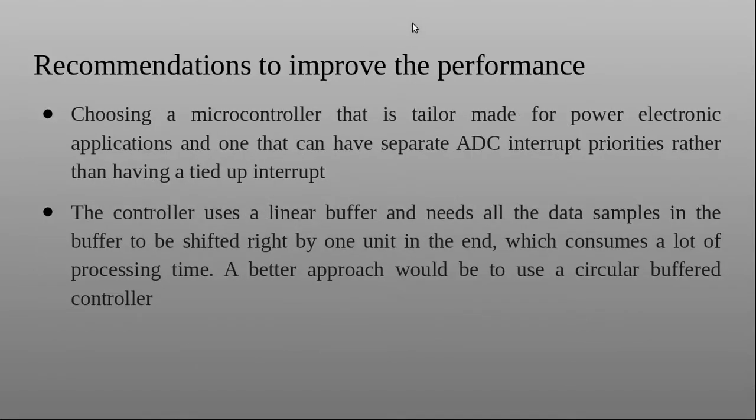Coming to the recommendations to improve the performance, choosing a microcontroller that is tailor-made for power electronic applications, and one that has separate ADC interrupt priorities rather than tied-up interrupts, can improve the performance of our system, and we can individually service each ADC interrupt whenever it comes in. The controller uses a linear data buffer and needs all data samples in the buffer to be shifted right by 1 unit in the end, which consumes a lot of processing time, and a better application would be to use a circular buffered controller.